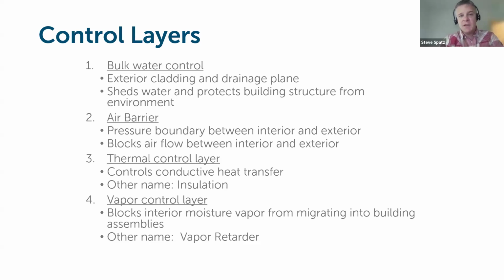So they will passively need to be able to manage the significant swings in temperature, pressure, moisture loading, season over season, and year over year. So that's why getting these control layers and the details right from the outset is critical. So we really have 4 layers that we're dealing with when defining any sort of framed building assembly. And we're talking about walls, roofs, floor systems, etc.